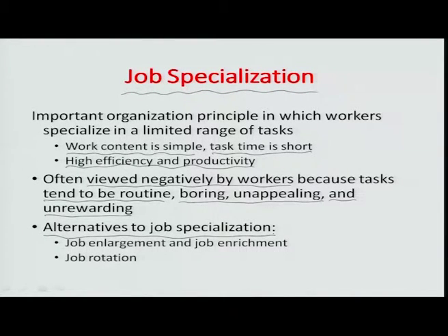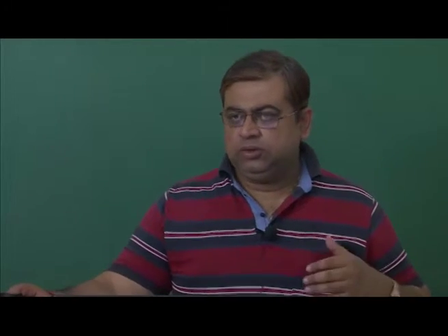For example, one can look into job enlargement, and I am going to treat these subjects individually in the following slides. One can look into enriching one's job by giving some level of decision making control. You are doing a task associated with, let us say, fitment of a certain component onto the assembly line of a vehicle, and as a worker you know that this assembly has a flexible system where there are many models and there is a mixed model production. So, maybe you can have a decision making role related to planning of materials which would go into your workstation and through your workstation onto the vehicle for the different models in advance. So, if you know that in today's particular shift there would be 30 different variants, it might give a better sense for an operator to look into the material availability near him and plan that exactly 30 different components of different types are being fitted into these vehicles.